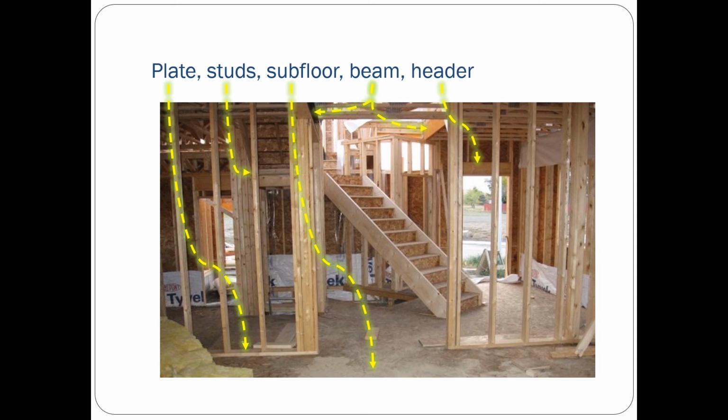On top of the foundation, we'd find joists, plates, studs, the subfloor, and above them are beams and headers. Some of these are structural components, which we cannot drill through, and it's important to us to understand and identify which of these are structural components that we cannot affect, and which of these can we go through without causing any injury to the building.